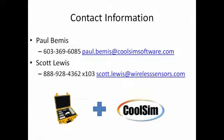The good news about the way that we've done CoolSim is you can do them concurrently. So you can do a sweep. You can say, I want to run it at supply air temperature of 60 degrees F, 65 degrees F, 70 degrees F, and 80 degrees F, and just keep setting up and kicking off those jobs concurrently, and they'll all run at once, and they'll all come back at once because they're running on a parallel system. So that's a fairly straightforward and fairly reasonable thing to do.